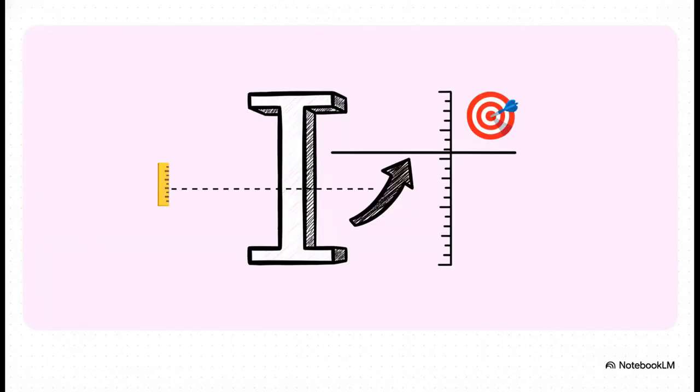So let's just put these numbers right next to each other. The geometric middle of the shape, which was an assumed reference point, is at 350 millimeters. But the true balance point, our calculated centroid, is way up at 440 millimeters. That's a pretty significant shift upwards, isn't it?